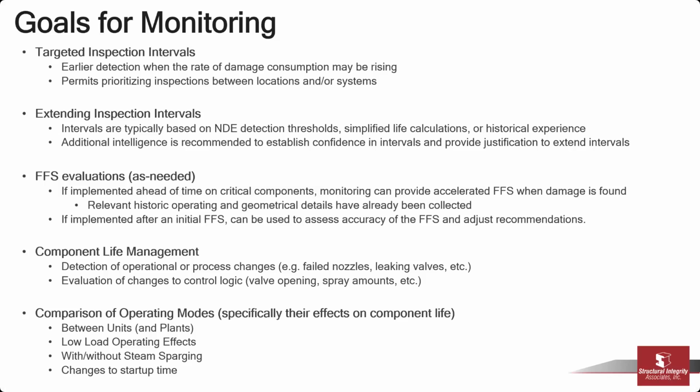So just going to check, see if I covered everything. We're able to compare the 3 units to each other, and that helps us to determine if there are any standouts, because all the units are identical. They should be operating in a similar configuration, similar loads, similar temperatures. So if something stands out, we can key in on that and figure out, is that an instrument issue or is there something going on with this unit that we need to investigate in a little more detail.